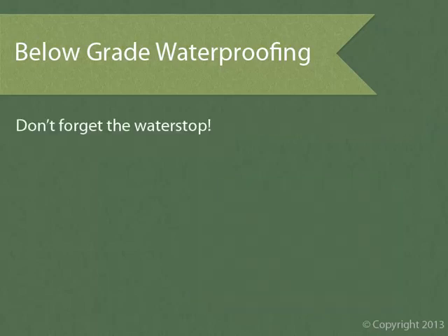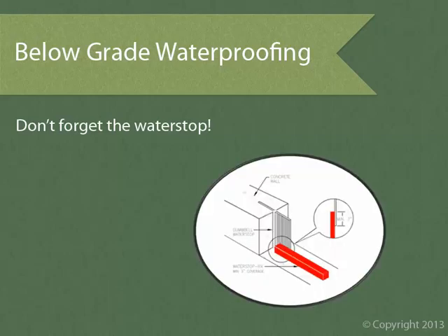Don't forget to show the water stop in your coordination details. Water stop isn't always shown on the architectural or structural details, so it's easy to overlook. In case you're not familiar with water stop, I've got a quick illustration here that shows two different types.